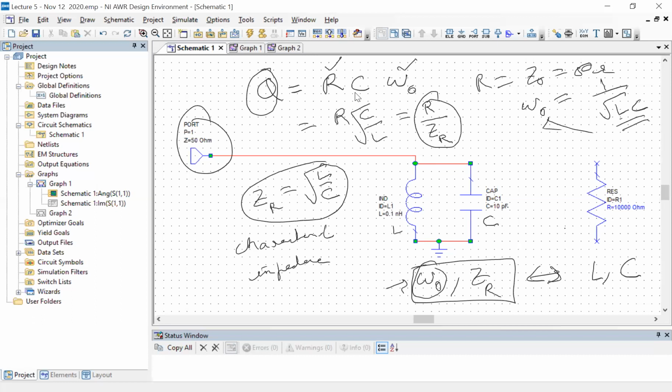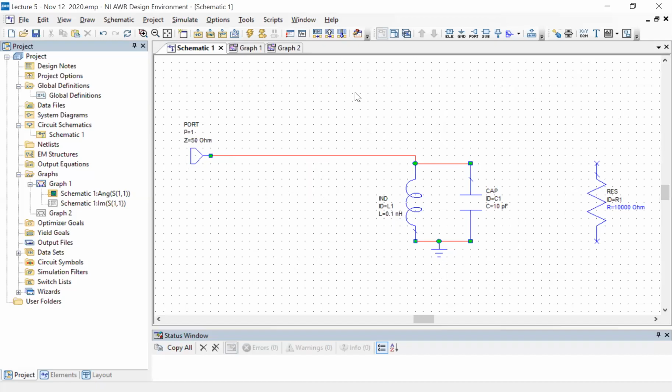Similarly with inductances, it's often very hard to go to very large inductances. Small inductances are easy, of course. So you see that this constrains what you can do with these, just playing around with L's and C's. And there could also be a situation in an experiment where these numbers are set by completely different considerations and you can't do anything about it. So then how do you change the Q factor? At least based on the simple formula, you still have only the option of changing R.